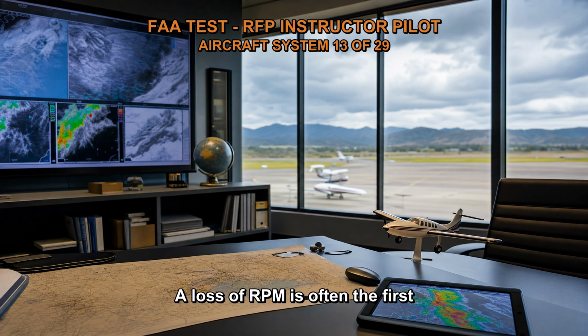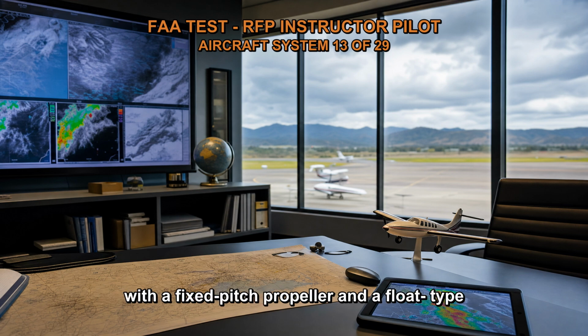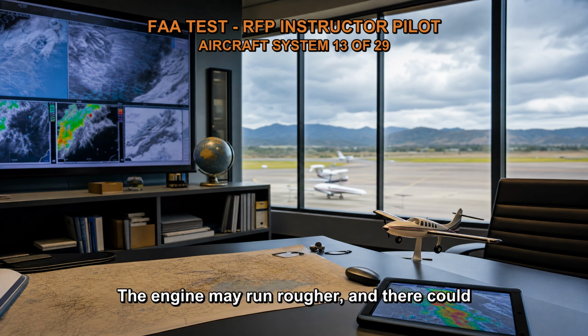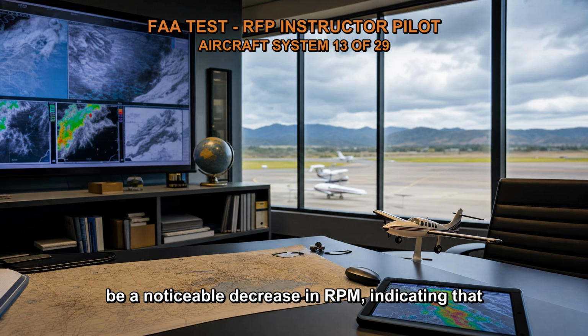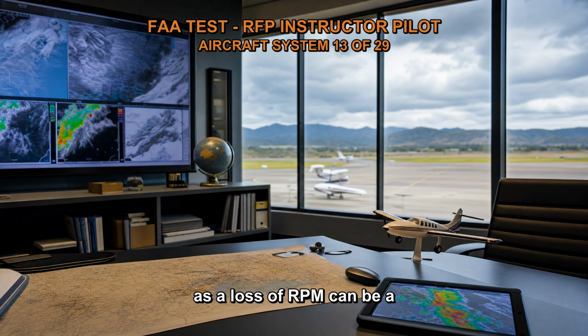A loss of RPM is often the first indication of carburetor ice in an aircraft equipped with a fixed-pitch propeller and a float-type carburetor. The engine may run rougher, and there could be a noticeable decrease in RPM, indicating that the ice is affecting the engine's performance. It is important for pilots to be attentive to any changes in engine RPM during flight, as a loss of RPM can be a warning sign that carburetor ice is present.